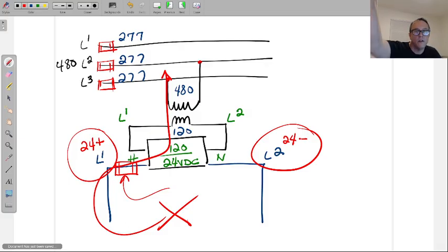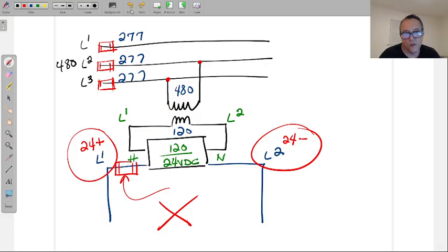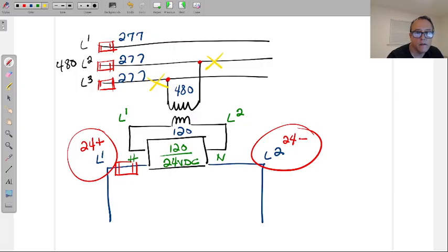We're not trying to protect the 480 volt system, the transformer, the wires, the fuses on the power side from 24 volts DC. What we're worried about is a short circuit happening up here, feeding into the transformer. Transformer is just a hunk of metal with some wires wrapped around it. So it's not going to stop this in any way.